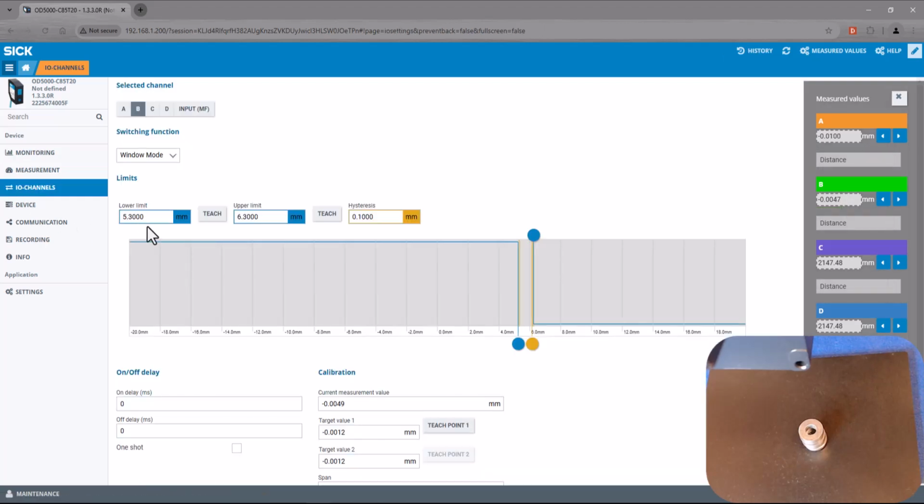This is just saying, when you send this measured value into your PLC, you can set up little windows like this and do it this way. So if it's within this window, then I know that 5 pieces have been taken off. If it's within different windows, then those correspond to different numbers of parts taken off.